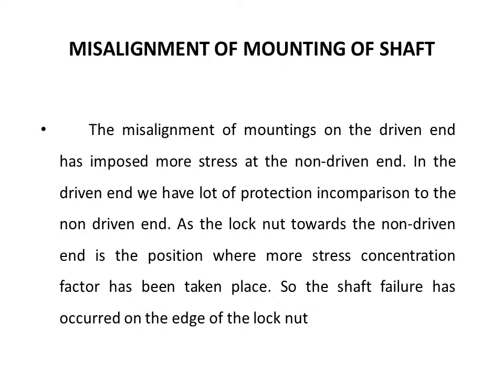Misalignment of mounting of shaft. The misalignment of mounting on the driven end has imposed more stress at the non-driven end. In the driven end, we have a lot of protection in comparison to the non-driven end, as the lock nut towards the non-driven end is positioned where more stress concentration factors have taken place.